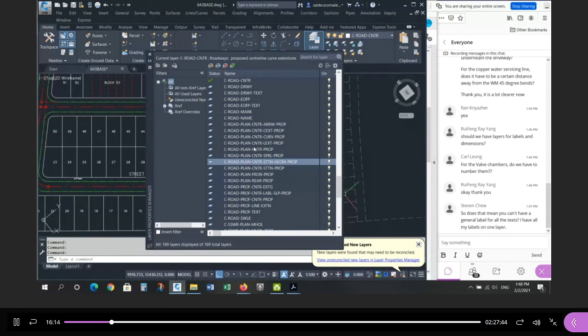And then you can easily manipulate the visibility states. You're going to go through the viewport on the Paperspace sheet and then turn off or freeze the layers you don't want to see. So if you mix them up, if you don't make it specific, then it's a problem. So I don't recommend putting the entire drawing text on one layer.